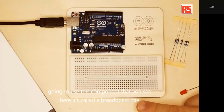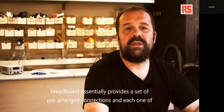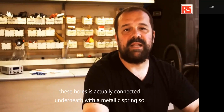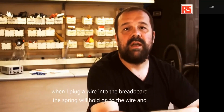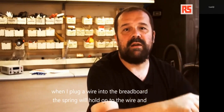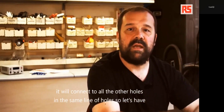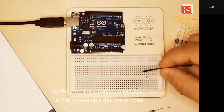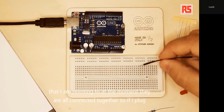It's called a breadboard. The breadboard essentially provides a set of pre-arranged connections, and each one of these holes is actually connected underneath with a metallic spring. So when I plug a wire into the breadboard, the spring will hold on to the wire and it will connect to all the other holes in the same line of holes. So let's have a look. For example, this line of holes that I am pointing to at the moment, they are all connected together.